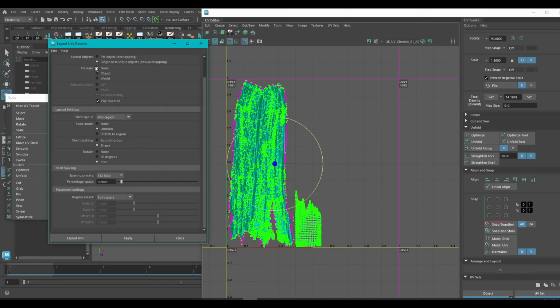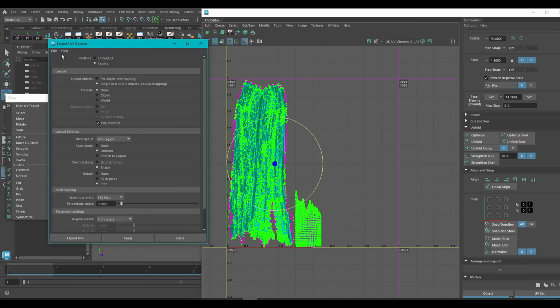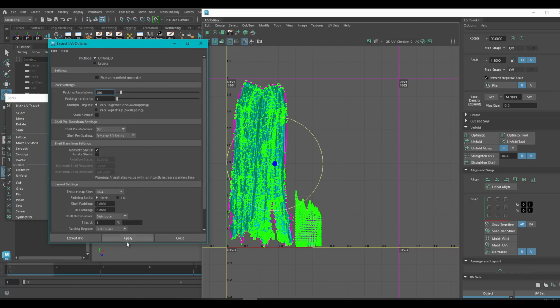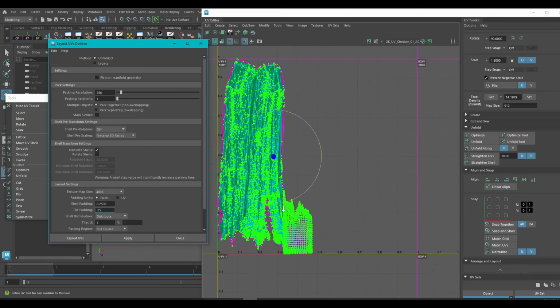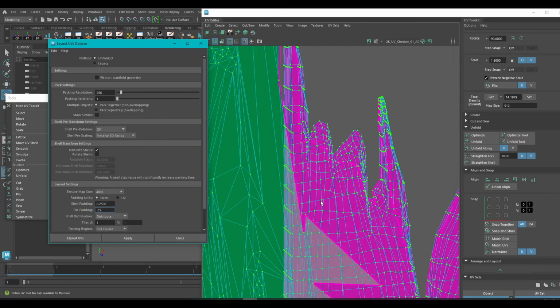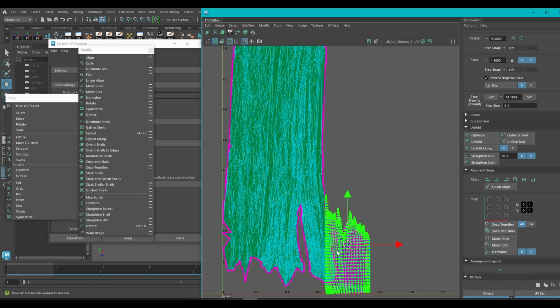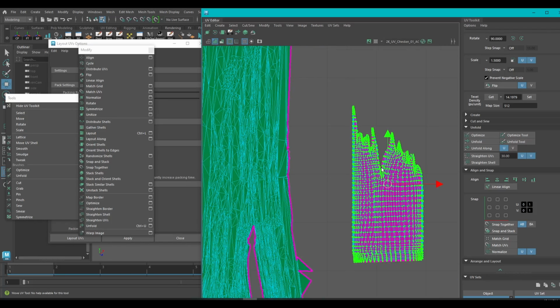Yeah, okay. Now you can go to unfold 3D and give the size you want. Then give the padding distance. I will use minus 25 and 25. That's it. But it's not giving now, probably because it's not unwrapped. Okay, we need to unwrap this one.